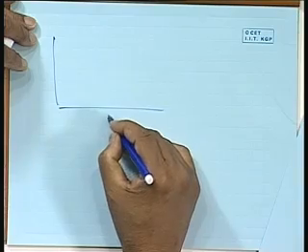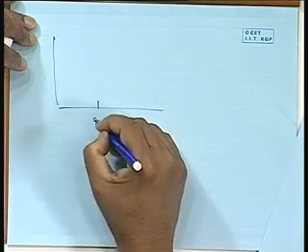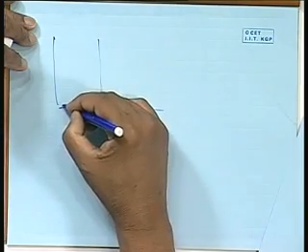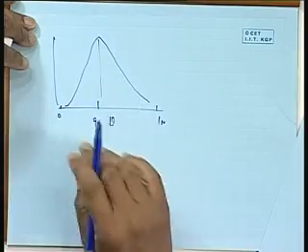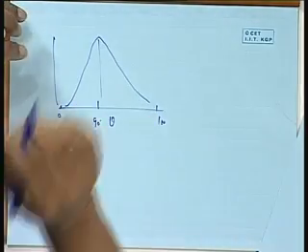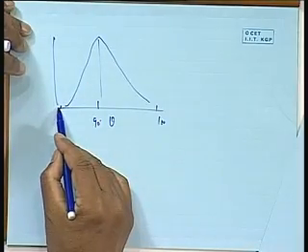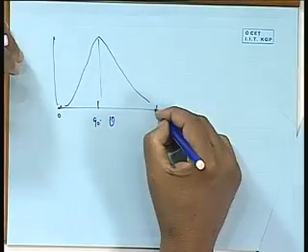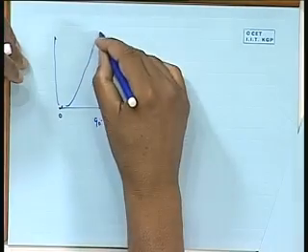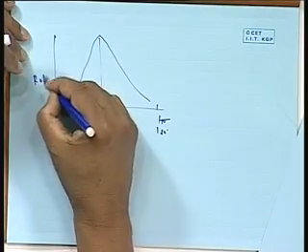What would happen? See, for example, if you take heading angle here, ship angle here, long crested waves, at 90 degree, you will find that the roll motion is very small here at 0 degree, very small at 180 degree, but it is very high like that, isn't it? See, if you take long crested sea, waves are all one direction. If waves are coming from the direction to which the ship makes 0 degree, that is following or head, no roll. There also no roll. Beam, there is much larger roll. You understand? This is roll.